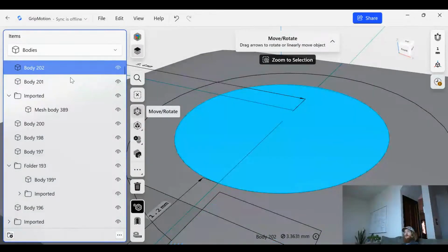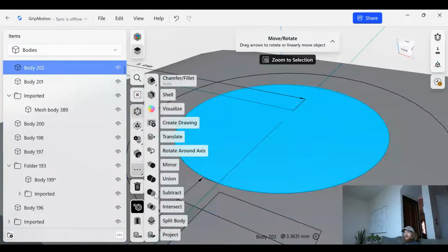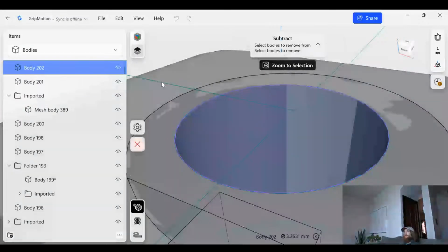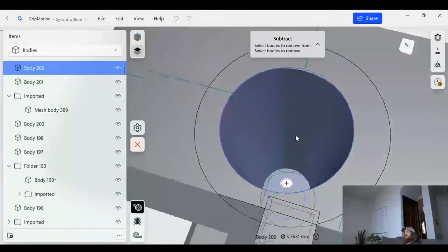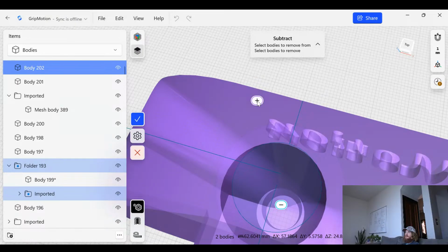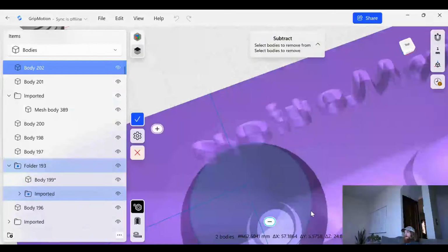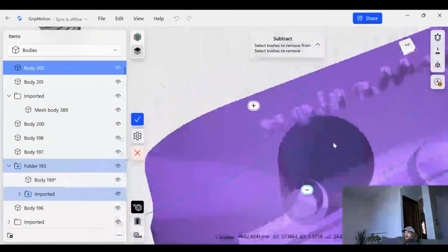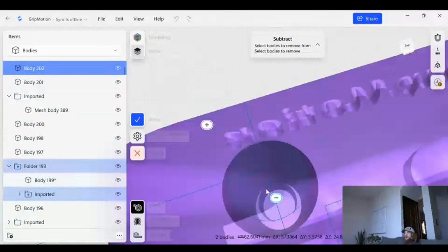I'm going to take that new body. I'm going to subtract, went to our three dots, highlighted the whole body. Subtract, right, an addition state, or this is what would be subtracted from. We're going to make this the subtraction from this primary body. And now we have a preview of our result on the interior. We could take a closer look, but that looks fine to me.